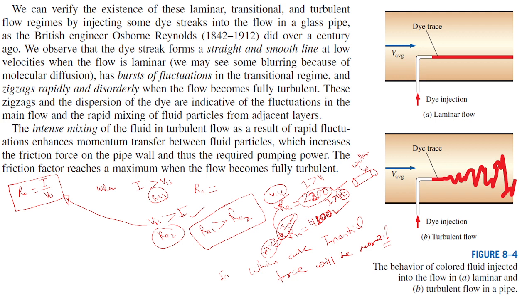So that is in both cases maximum, but we are comparing these two cases. In which case is inertial force more dominated? In the second case the mass flow rate is very, very high compared to the first. If your inertial force is more, when comparing two things, there are more chances for the flow to become turbulent. So here it is just qualitative. If you work it out yourself on pen and paper, you will understand more easily.